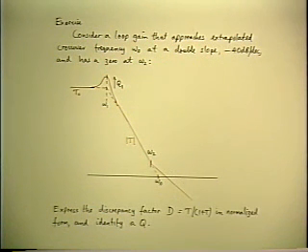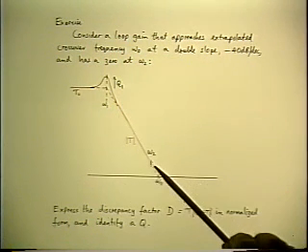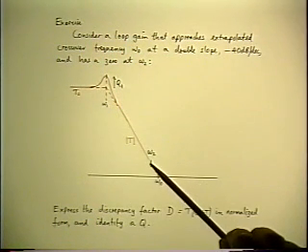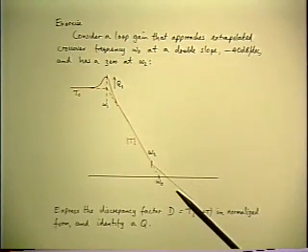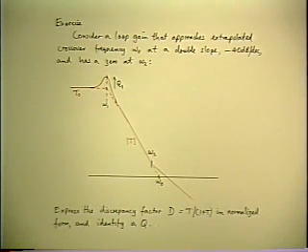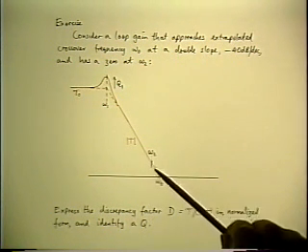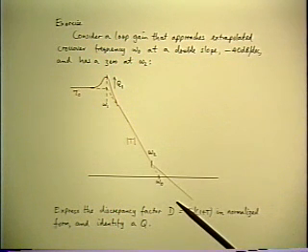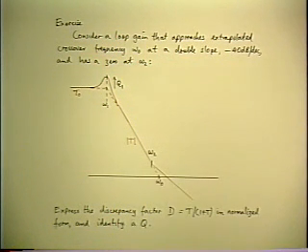And then when they started buying the capacitor from a different place, the ESR was lower, and the zero moved out, so they didn't have as much stability margin as before, and moreover, ESR goes down as temperature goes up. So at high temperatures, the corner moved even further out, and sometimes it moved out far enough that the stability margin went away altogether, and they had an oscillator on their hands and an unhappy customer.